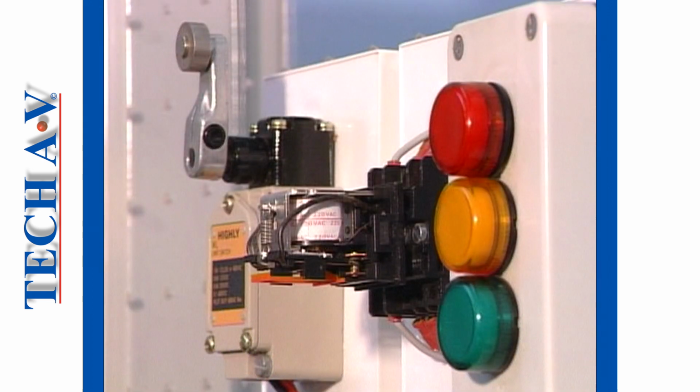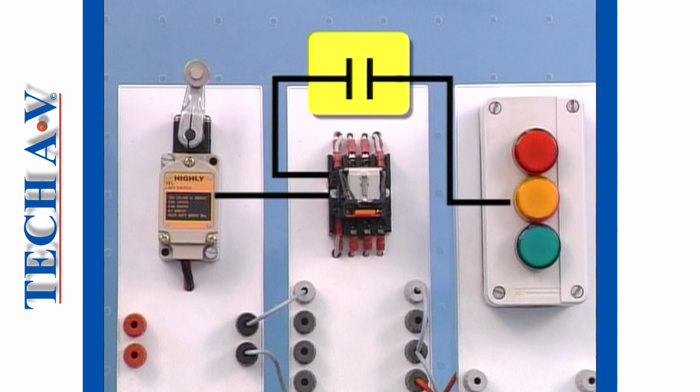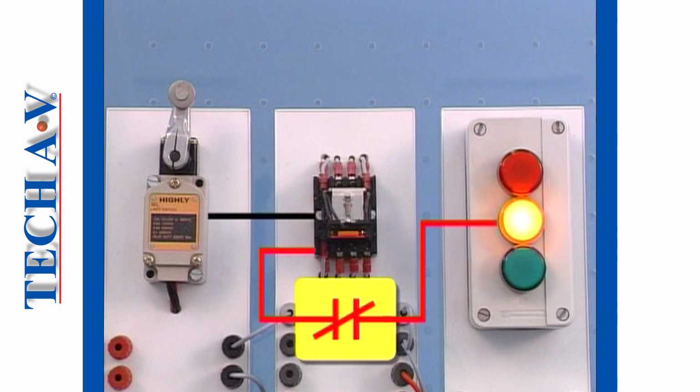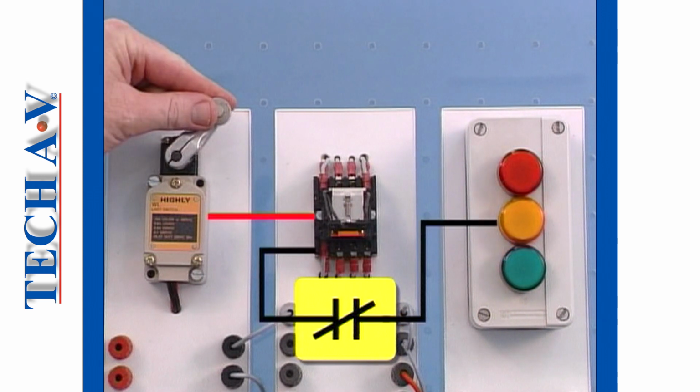We've used an actual relay circuit to explain the operation of this imaginary relay. A lamp is connected to the normally open contacts, and the limit switch represents our external input device. When the switch sends a yes or on signal to the relay coil, its normally open contacts close, switching on the light. Now we will rewire the relay circuit, but this time we will connect the lamp through the normally closed contacts. The lamp remains on until the switch is activated and the normally closed contacts open, switching off the light.